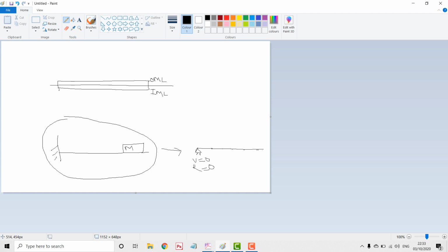And coming to the dead mass, it's not a force, it's just a mass. So what I can do is model a rigid element and then model a mass element over here, which is a point element. What it will apply is a mass, something like weight. So the weight will be applied on the beam. Instead of a force, you are modeling it as mass.